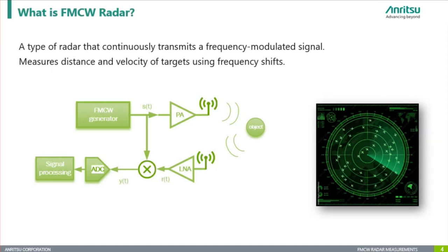If you look at the block diagram of FMCW radar, the radar system generates a frequency modulated signal using a triangular waveform applied to a carrier frequency. This modulated signal is passed through a power amplifier to boost the strength before being transmitted via the transmit antenna. A separate receive antenna is used to capture the reflected signals, with sufficient isolation between the antennas to minimize leakage and interference. The reflected signal is fed into the mixer where it is combined with the original transmitted signal.